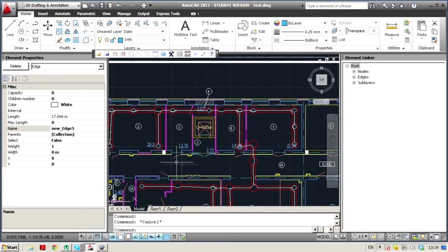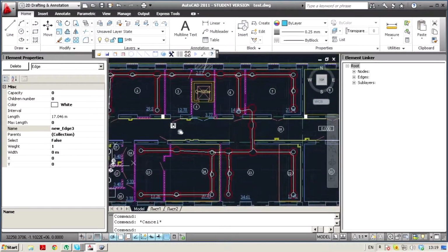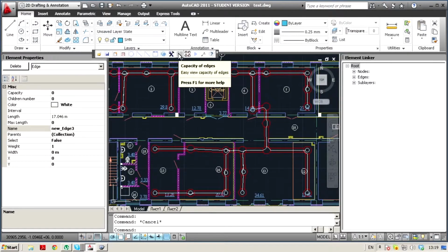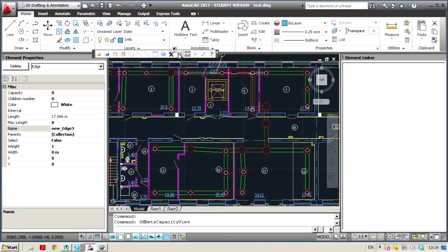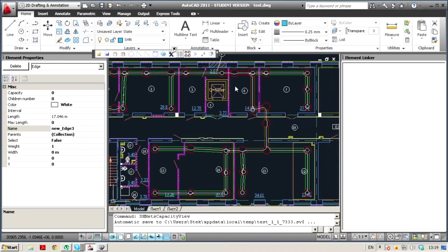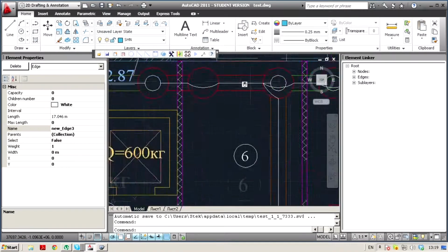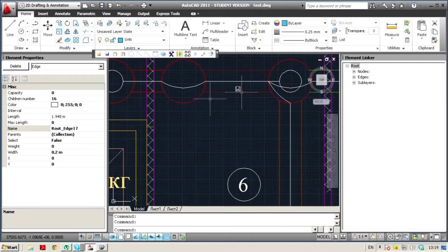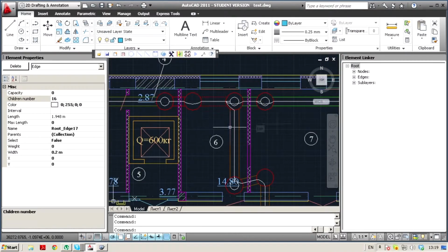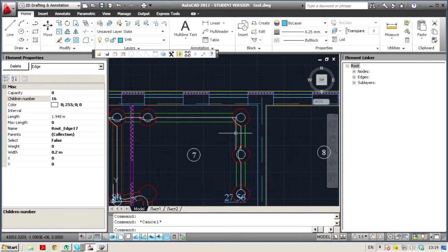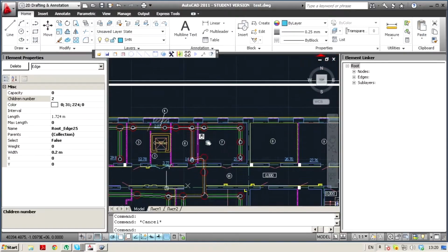NetGen has a tree of objects where you can see all the objects currently on the network. Additionally, NetGen has incorporated functions for network analysis. For example, you can determine the network load of each route by using a special tool labeled capacity. You see the network painted in colors from red to green. The red cable channels are almost full, and the green channels still have space for cables. We can see how many cables are set into a specific cable channel.